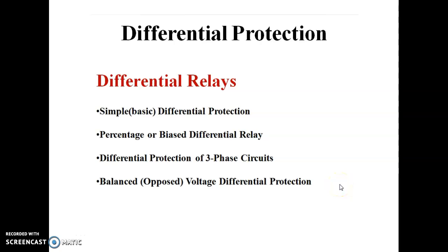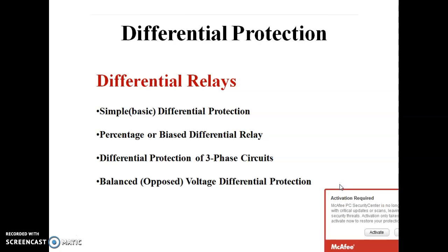Hi everyone, now we are going to discuss differential protection, that is in the third module, second part. In this type of protection we are going to discuss how to identify an internal fault, usually by comparing the electrical conditions in the electrical equipment, that is, the entering current and the leaving current. We have to measure the difference between them and protect our electrical equipment.